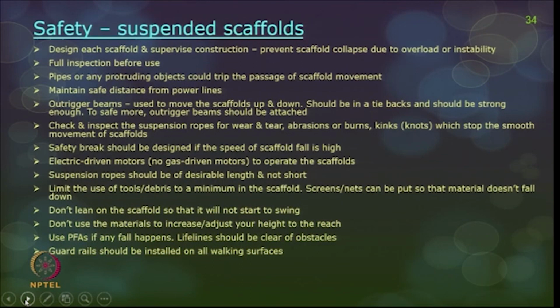Now, we will talk about the safety precautions. Again, as I told, all scaffolds should be designed, constructed and erected under the supervision of a skilled person, and you should take proper care while designing and constructing these scaffolds. Design each scaffold and supervise to prevent scaffold collapse due to overload or instability. A competent person should do a full inspection before using the scaffold, and every time you start using the suspended scaffold, it should be fully inspected and only then used.